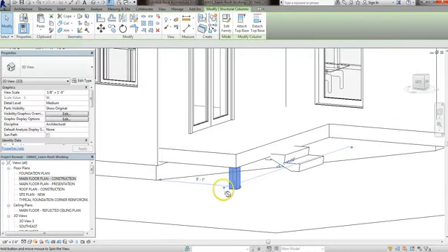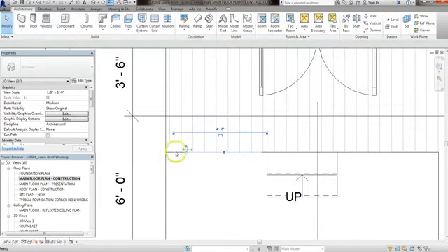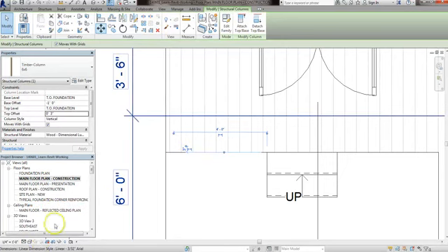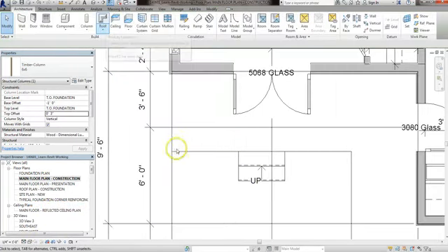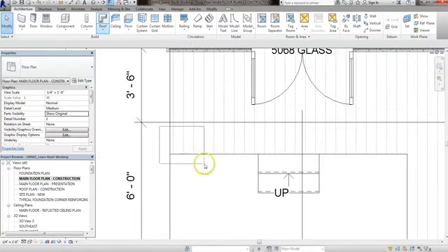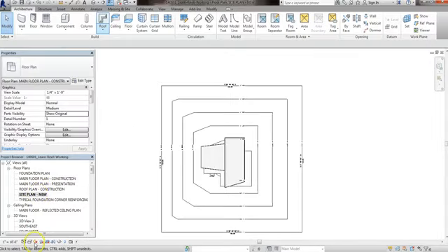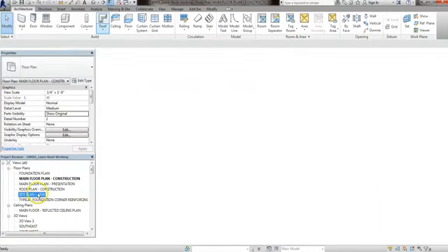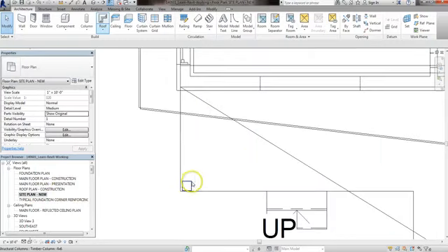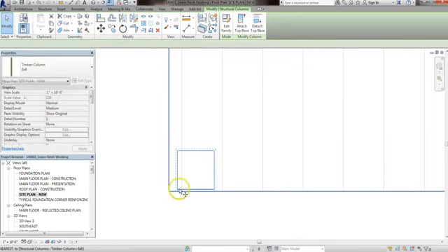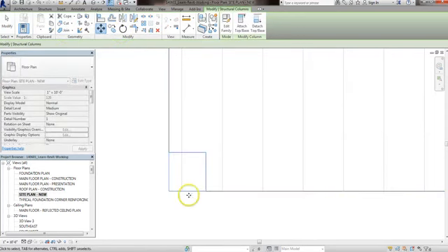You can examine it more. You can adjust it more. But let's go back. Let's change our view to hidden line. Why aren't we seeing that? Let's go to our site plan. Wireframe. There we go. Was I in wireframe over there? I was, but it's not allowing us to see it. So we can go to our site plan. We can click on that, hit MV for move or find your move button up there. Click on the corner, put it in its place.